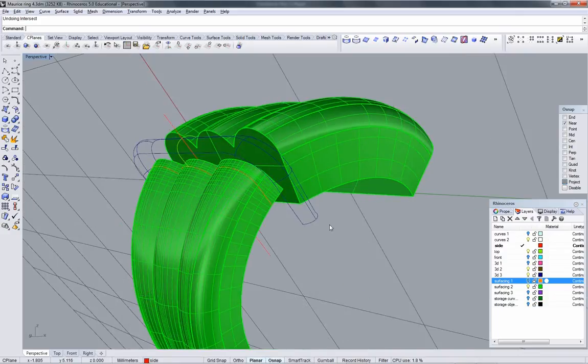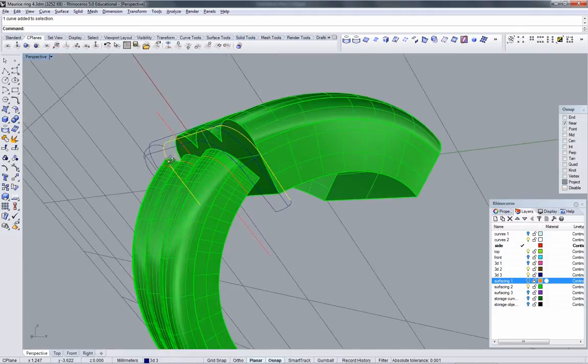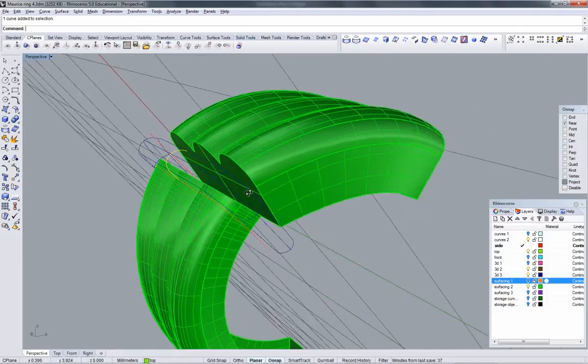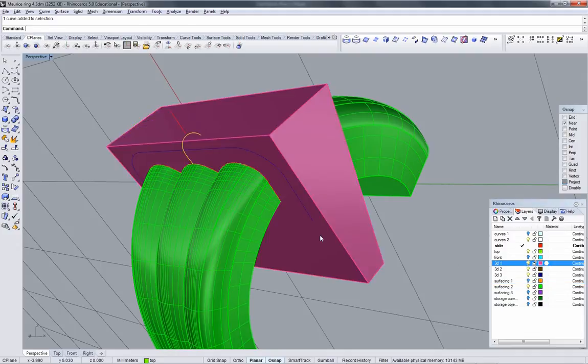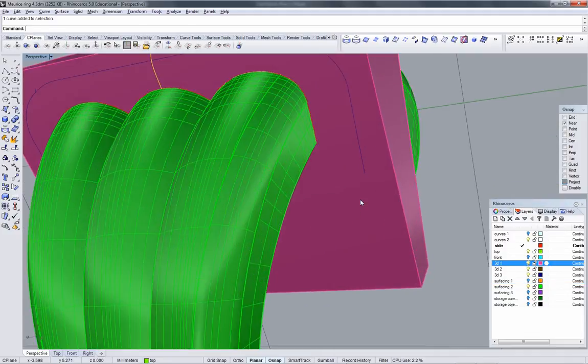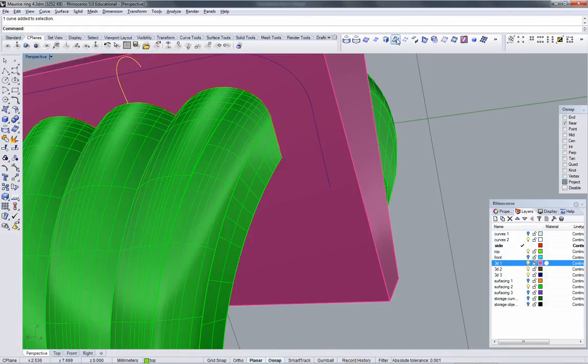I'm not going to want to count on a fillet to treat the edge of this, because I already have this cross section, which is self-filleting. So for the rest of the cross sections, for this back section, I have to do the same thing. It has to be self-filleting. So extract iso curve.